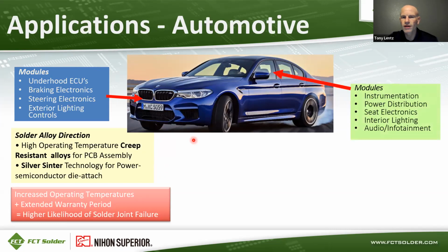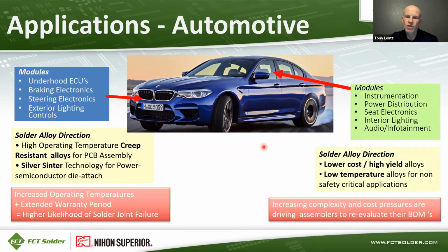There's also electronics within the cabin of the car, including instrumentation, power distribution, seat and lighting electronics, and of course the audio or infotainment systems, which seem to be like fully functional computers in cars these days. Solder alloys that are being used in those applications are lower cost or higher yield alloys, and in some cases low temperature alloys can be used for non-safety critical applications.